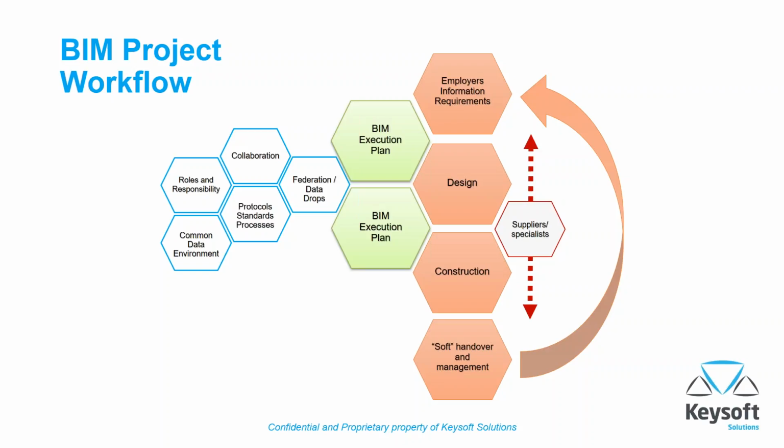And this is done through setting standards such as data drops, key points or milestones where data is pulled together to check: are we on budget, are we on time, are we meeting the program requirements of this project? We also set protocols, so standards such as units, base points, and a schedule to update our common design environment. We need to set up a schedule to test the model. This needs to happen early and at a set interval.